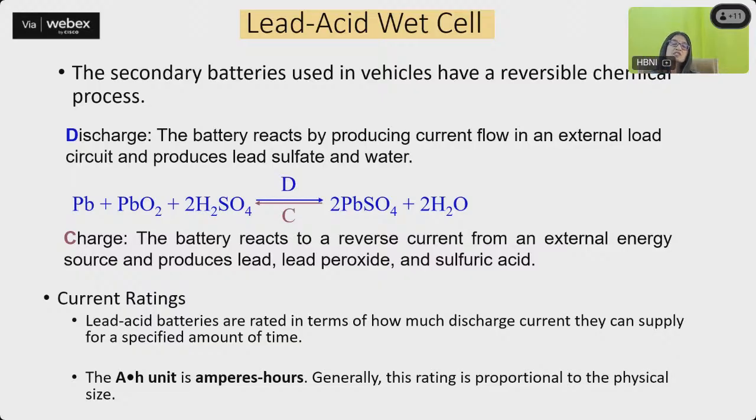Suppose we have a lead acid battery and it is discharged to some extent. How do you know the state of discharge, or the state of charge, of the battery? You will measure it with the specific gravity. You will measure the specific gravity of this lead acid cell and find out to what extent it has been discharged. Why? Because when it is getting discharged, it is forming water, so the specific gravity of the material changes. By checking the specific gravity of the electrolyte, you should be able to make out what percentage of the battery has already discharged.